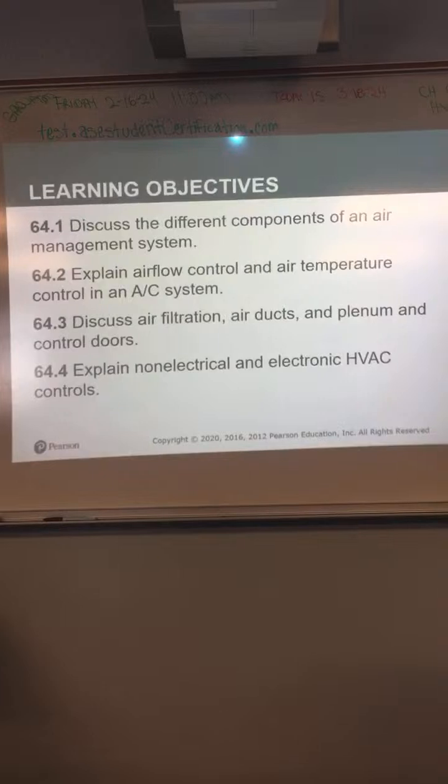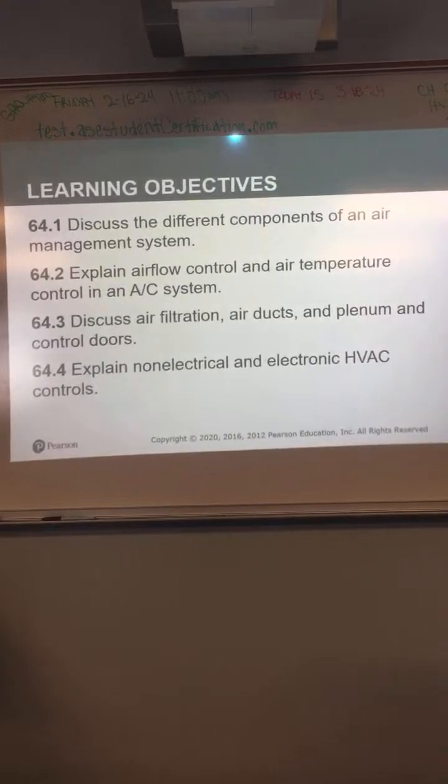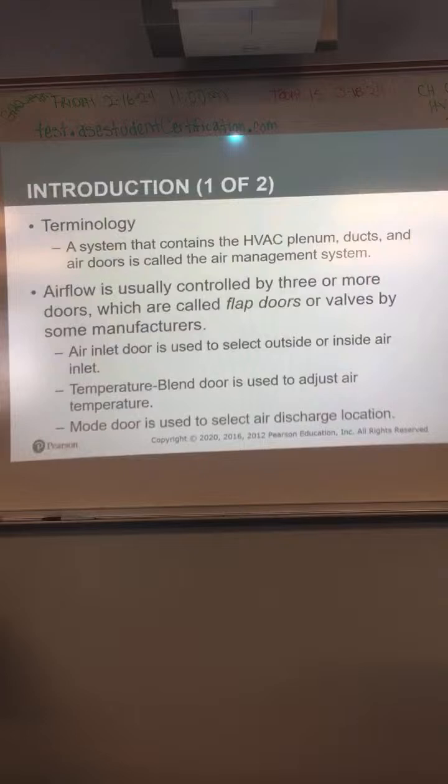Different components in that air management system: airflow control, temperature control in the AC system, filtration, obviously the cabin filter, the air ducts that get it where it's going, control doors, the plenum, which is the big unit inside the car, and non-electrical and electronic HVAC controls. The system that contains your HVAC plenum, ducts and air doors is called the air management system.